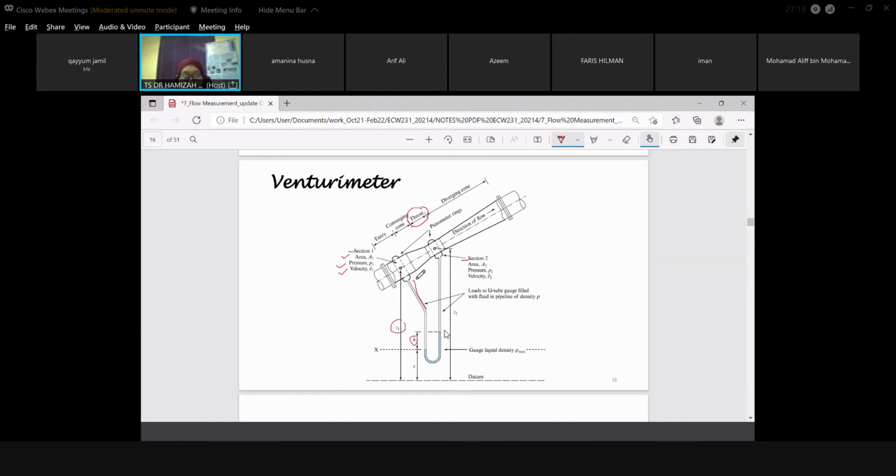Okay, we cannot measure any inclined plane. So if the pipe has an angle, you need to use the Pythagoras theorem to find the vertical height. For example, we have an inclined plane of 2 meters, but we don't want to use this as the elevation because this is the inclined height. So we need to find this one, Y, the vertical height.